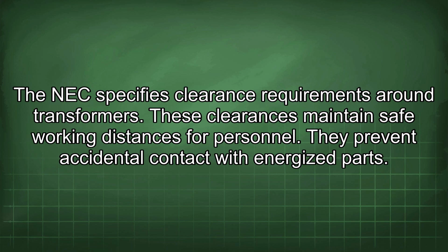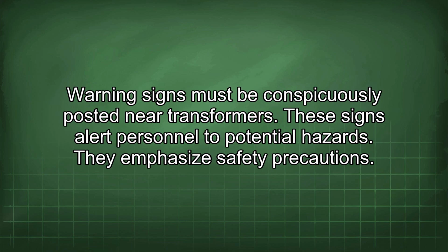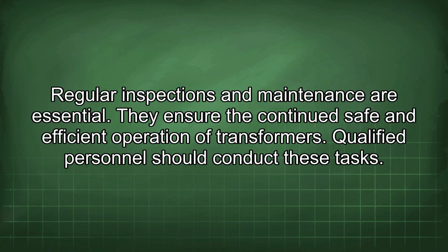The NEC specifies clearance requirements around transformers. These clearances maintain safe working distances for personnel. They prevent accidental contact with energized parts. Warning signs must be conspicuously posted near transformers. These signs alert personnel to potential hazards. They emphasize safety precautions. Regular inspections and maintenance are essential. They ensure the continued safe and efficient operation of transformers. Qualified personnel should conduct these tasks.